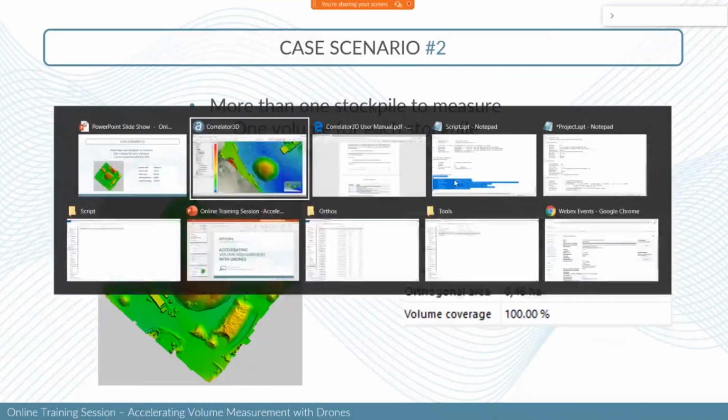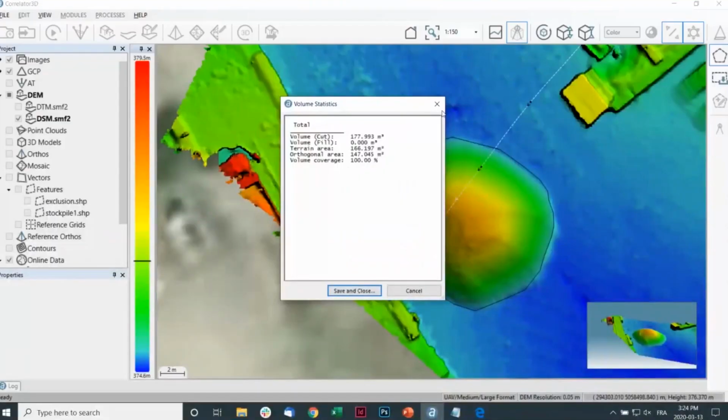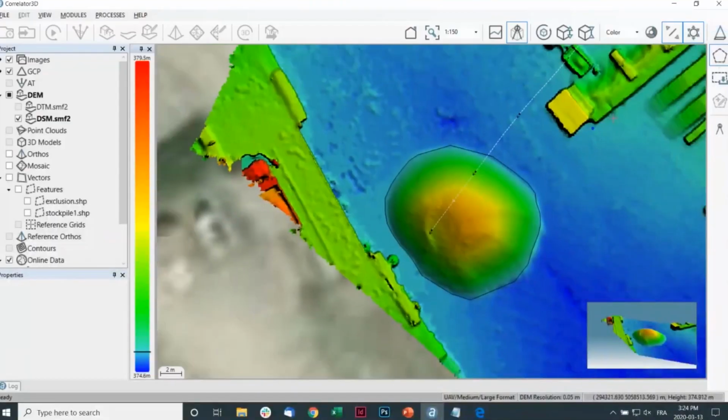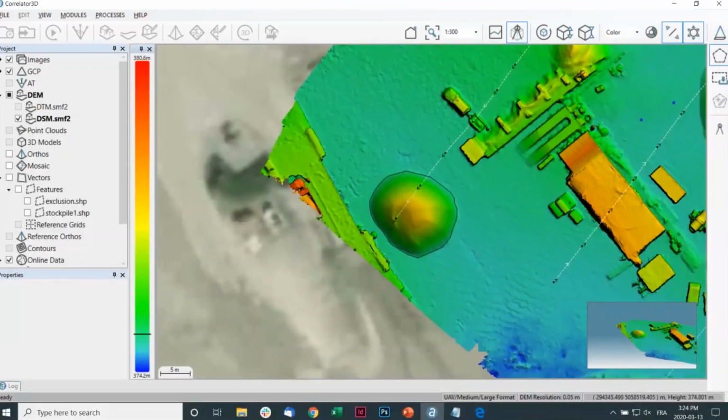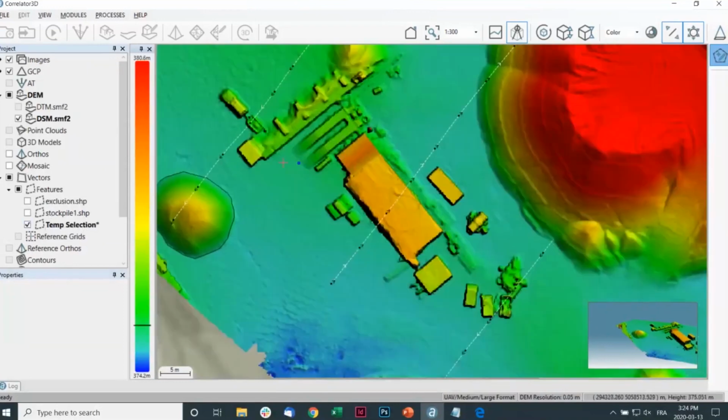So as we can see here, let's say you want to create a new shapefile. So let's say I have already drawn a polygon like this, and I want to add one to the specific selection. I could save the selection to a file, and then it will create a temporary selection in my feature tree, and then I could add another selection and draw a polygon.